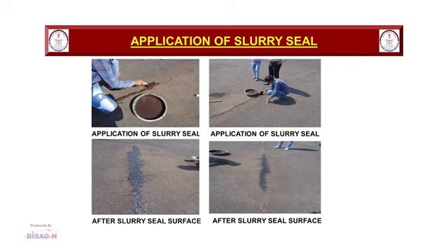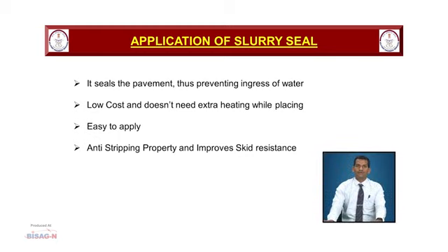for the next 12 hours. Coming to the advantages of the slurry seal, it seals the pavement, thus preventing the ingress of water, is low cost and doesn't need extra heating while placing. Slurry seal is easy to apply, has an anti-stripping property and improves the skid resistance.